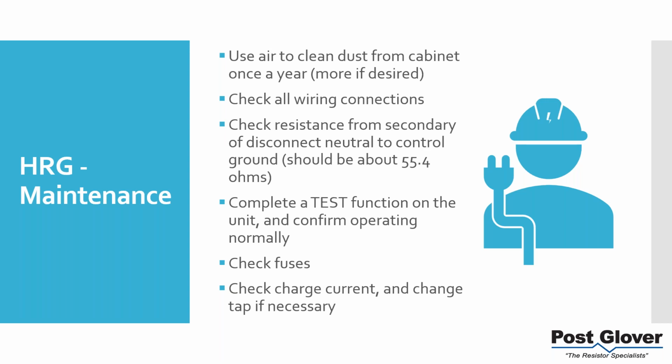Check fuses. That's kind of an obvious one. Do that with all your stuff. Check the charge current. This should not ever change unless you add stuff to your system. But once again, that happens. So I would just always check it if you're adding stuff to your system. But if that didn't happen, just make sure it's part of your maintenance schedule, and make sure the charge current is low enough.